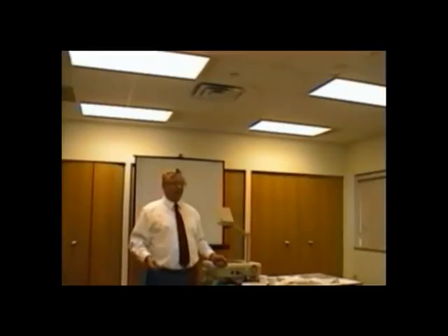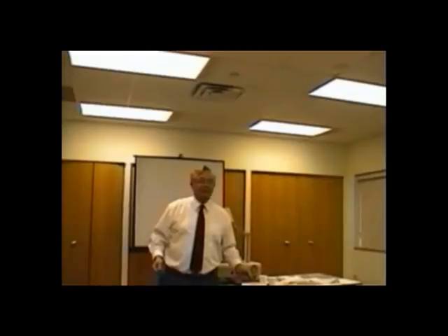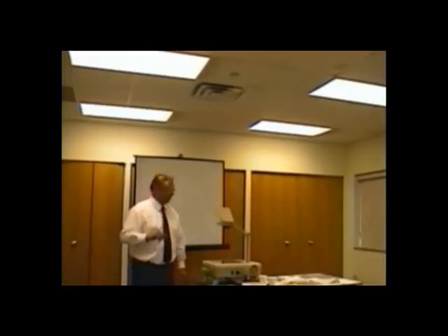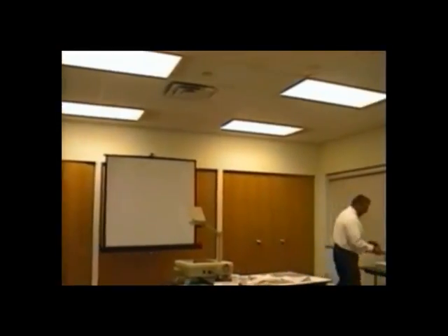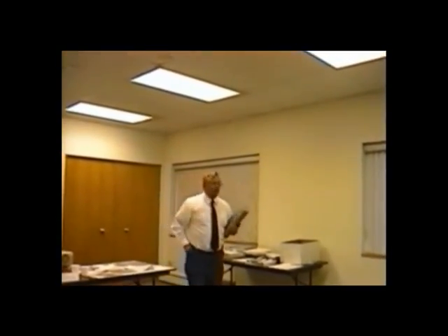Today we got scales that are in increments of 1/10 of an ounce. So 51.7 is a piece of cake. Let's talk about this a little bit. I'm going to grab the scale over here. And all we're saying to you is it's going to take you longer to figure out the refrigerant charge than it is to recover and recharge.